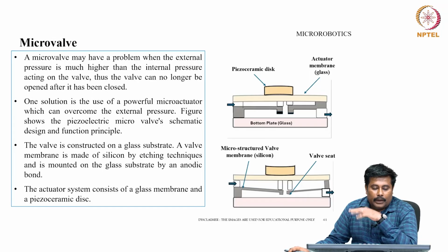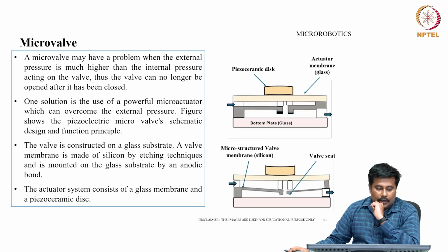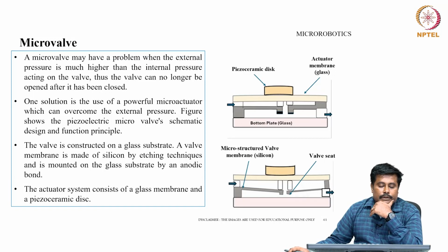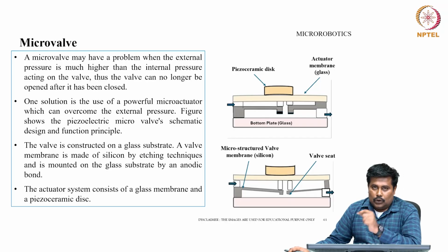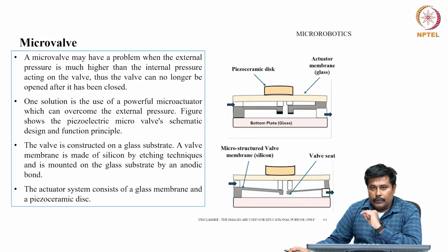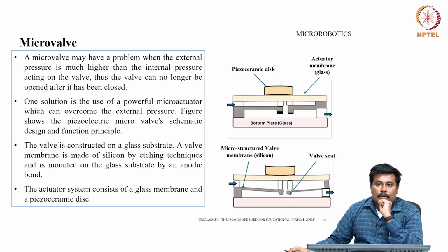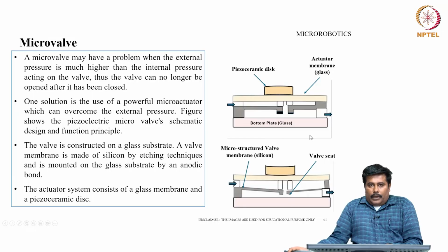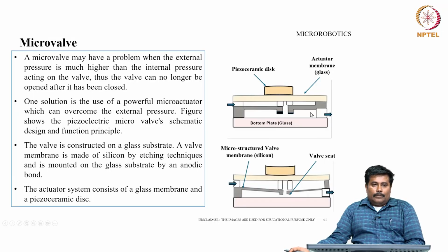As far as a micro valve is concerned, it may have a problem when the external pressure is much higher than the internal pressure. The valve can no longer be opened after it has been closed. One solution is the use of a powerful micro actuator which can overcome the external pressure, and this is a kind of system which shows a piezoelectric micro valve schematic.